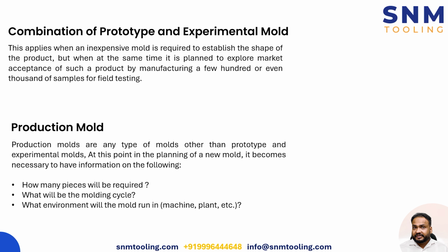Because shrinkage is something which can change the dimensions or tolerances, which is why very tight tolerances are not really possible in plastics. But still, efforts have to be made in this direction to at least contain the dimensions within the tolerances, even if they are on a looser side.